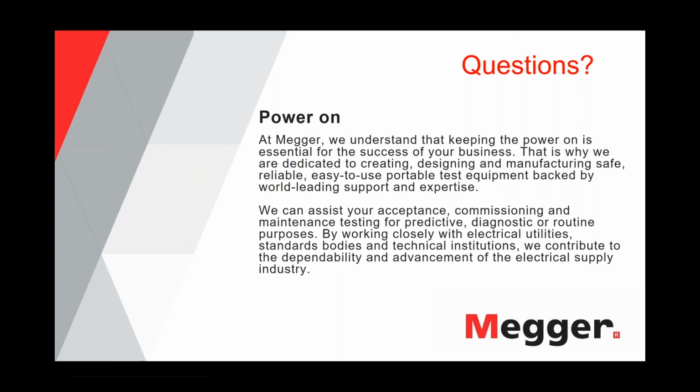So you have a little bit of wiggle room there, because the tan delta is in terms of stress below the withstand test in terms of how high you go with the voltage. And that also helps because the machines have a load curve, right? And if you go down in voltage compared to the maximum what the machine can do, you also gain a few percent on test capacitance.